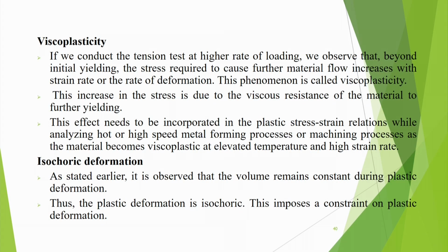Okay. So now we discuss what is viscoplasticity. If we conduct the tension test at a higher rate of loading, we observe that beyond initial yielding, the stress required to cause further material flow increases with strain rate or the rate of deformation. That means it is dependent on the rate of deformation. If you conduct the test at a slow strain rate, you will have a different observation. If you conduct the same test at a high strain rate, you will have a different observation.